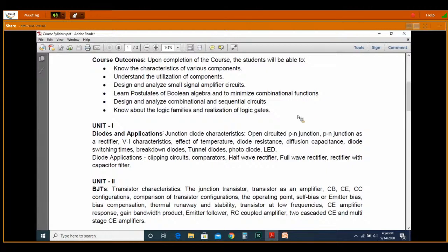In the reverse bias, there is no current flow theoretically, but practically a reverse saturation current is flowing through the PN junction diode. Now what is the effect of temperature? Whenever temperature increases by 10 degrees, the reverse saturation current doubles. Reverse saturation current increasing means ultimately the problems also increase in the practical side. So we are going to reduce the leakage current. That is our main concern.